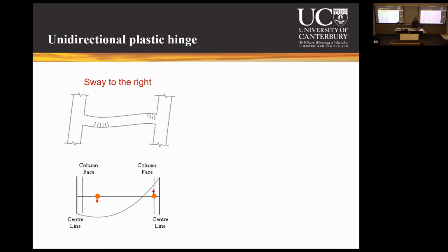It doesn't necessarily mean that the seismic demand should be low, but even if the seismic demand is reasonable, if you use a very high ductility factor to reduce the seismic design force, then the gravity action can become significant in comparison, and you will get negative and positive hinging at different locations.